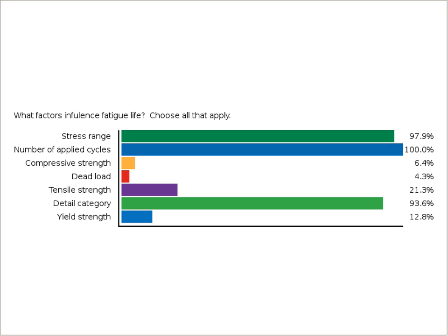So in our structures, in fabricated steel bridges, tensile strength really has no influence on fatigue life. If you had polished steel and you had different strength steels, tensile strength would make a difference. But that influence is very, very small as soon as you would weld the steel or cut a notch in it or drill a hole in it. The effects of how we fabricate effectively erase any of the improvements you would see by improving the strength of the steel. Higher strength steels that would be polished would exhibit a higher fatigue resistance generally. But as soon as we fabricate them, all that goes away.